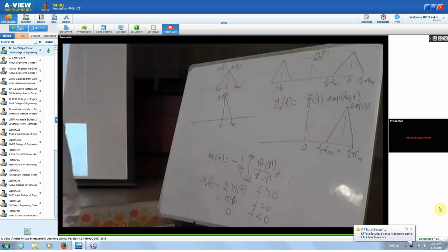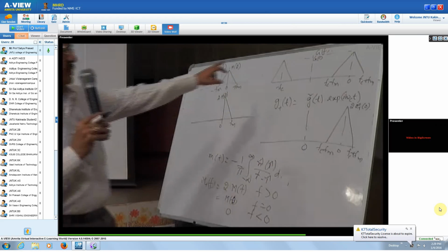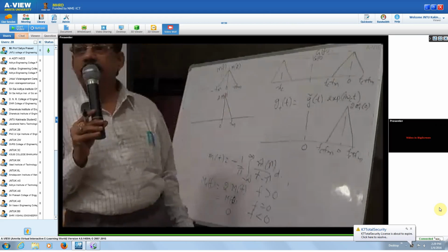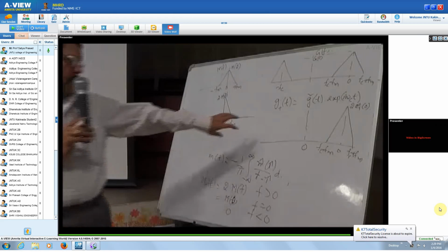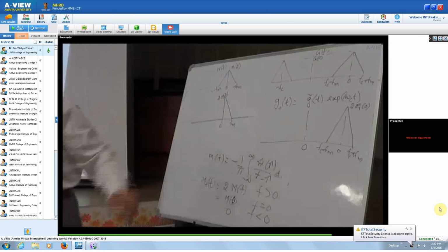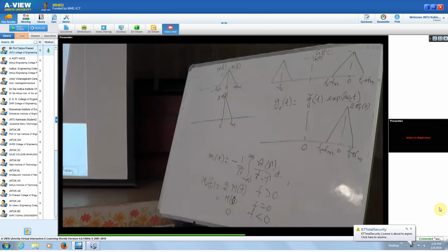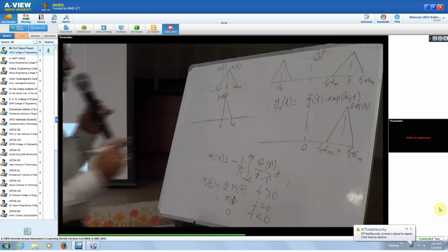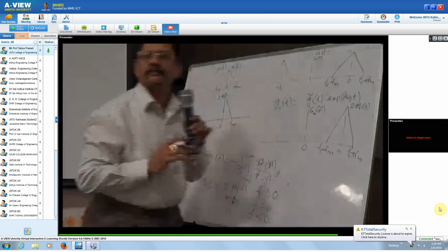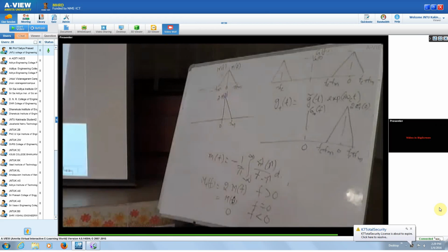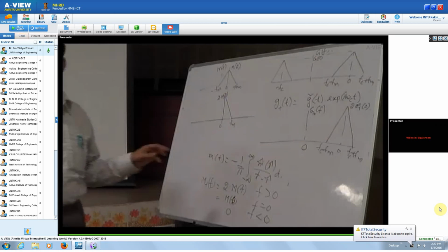Anyhow, forget about the coefficients. So you are going to get twice that with negative frequencies being 0. This is your pre-envelope signal, G plus of f, the pre-envelope of our signal G of t.